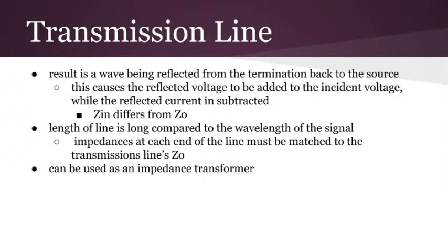So a waveguide in circuit theory is described by a transmission line that has a length and a self-impedance. The impedance is the resistance of the circuit component, which is the waveguide here, and the propagation of the wave. So the transmission line is terminated in some impedance, let's say ZL, and that impedance is different from the characteristic impedance Z0, which results in a wave being reflected from the termination of the transmission line back to the source.